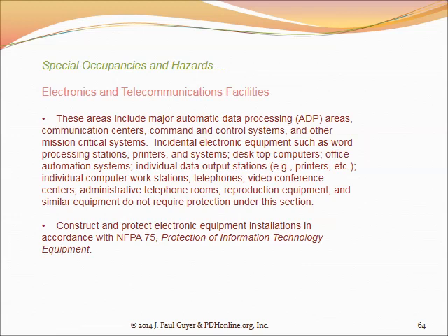And this was a gas fire suppression system, but one of the concerns with a gas fire suppression system, like CO2, carbon dioxide, is that carbon dioxide is a hazard to human beings in the space, and so it was not appropriate to discharge CO2 to put out a fire in a computer room because of the risk to the human occupants. So Halon 1301 was initially developed